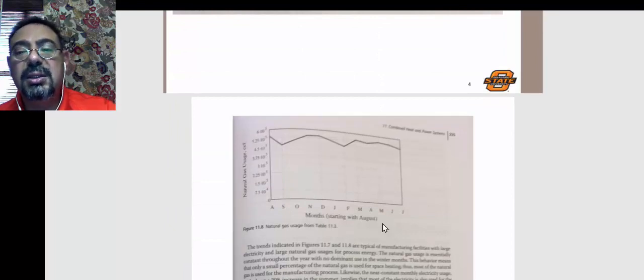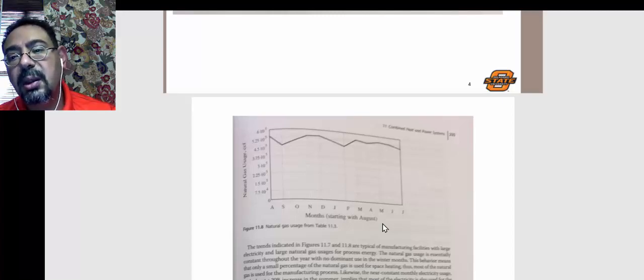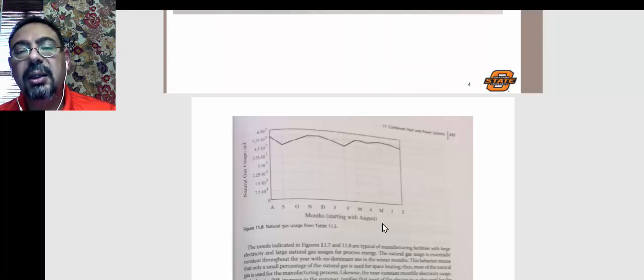So now, in order to convince the hotel manager or the hospital administration that this is a great idea, there are certain conditions that need to be satisfied to make that worth the effort. Okay, what's the effort? You're gonna buy a steam power cycle and put it in your hotel. It's expensive, right? And it doesn't have to be a steam power cycle. You can just buy a small gas turbine, and then the exhaust, you will use it for heating. That would be combined heat and power production. Well, that gas turbine is gonna cost a lot of money.